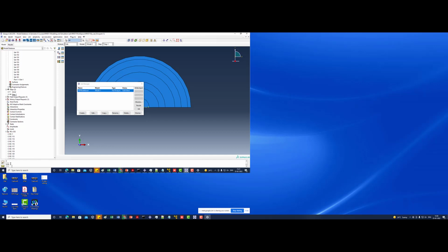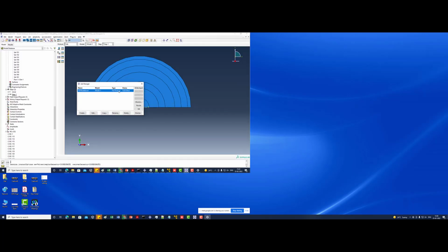Control V and enter. So this is session.journal options set value to coordinate. So instead of masking in the code, it will give all the values. So you see here that it is selecting some of the edges, some of the faces, some of the nodes with a masking scheme. So that will not be there if we use that command.